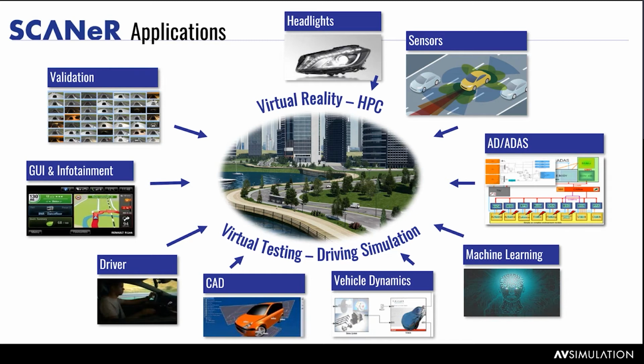So, being, for instance, drowsiness, or the driver maybe being tired and starting to fall asleep at the wheel. This is the kind of human factors, stress factor too, that you must encounter when you design ADAS systems. And so Scanner allows you to either simulate these human factors through scripting, or actually put an actual driver in the loop, because it's also a driving simulator. So put an actual driver in the loop and connect them to Scanner, and monitor their behavior or their biometric data.